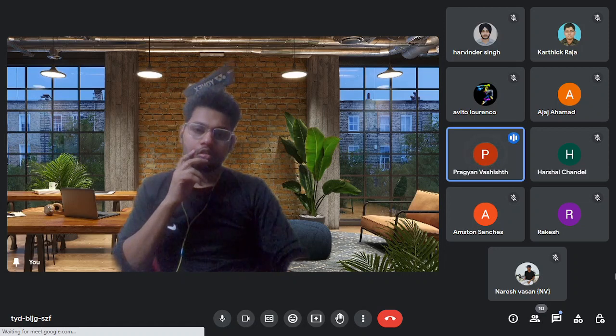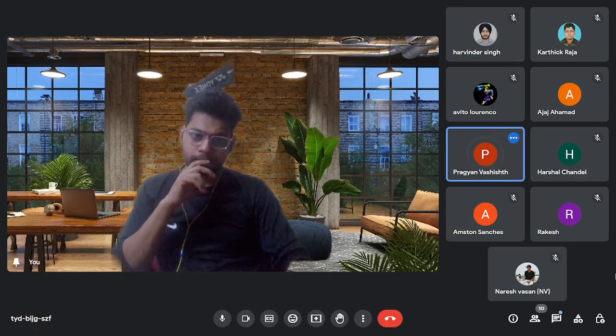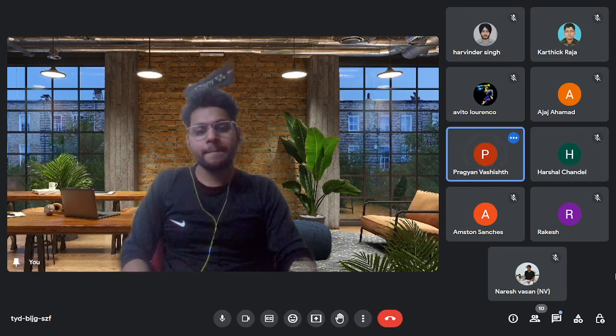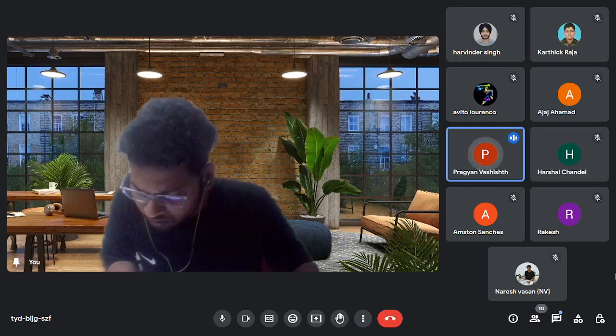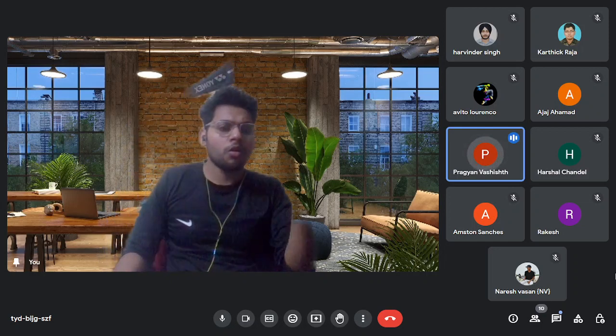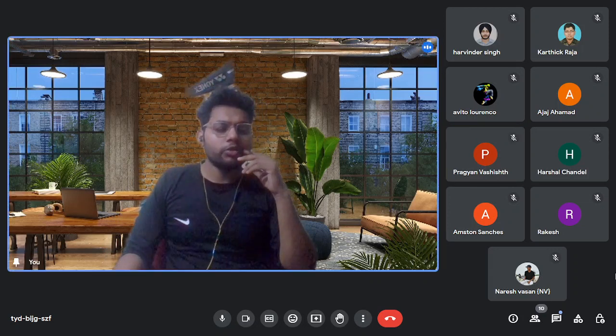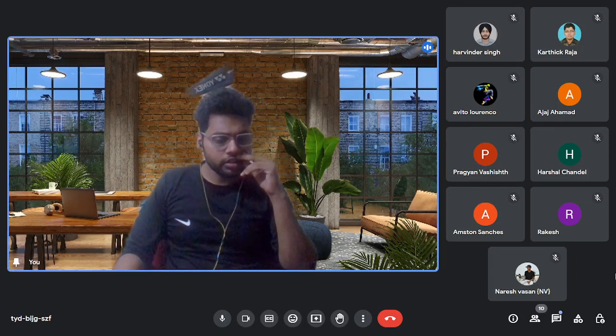Okay. And it's the best method with which we can test, because it does not spoil the material like dye penetration testing, and it covers all the materials. Like in magnetic particle testing, we can only use ferromagnetic substances, and we cannot test non-metals with magnetic particle testing, right? So it has certain limitations, but ultrasonic is the testing we can do for all the materials. Okay. All right. Vito, have you any idea about this technique, this ultrasonic testing method?